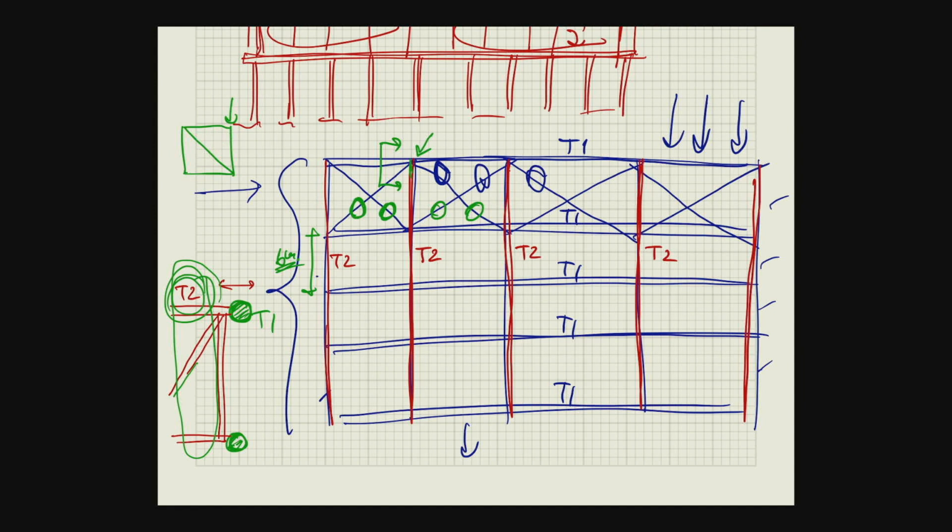Whereas if you have the load in the opposite direction, then this one carries the load because it is in tension, whereas this one is in compression. Compression is going to form some sort of elastic buckling. There is no permanent deformation in your brace as it is really slender. So the brace is generally made of maybe deformed bar or tie rod, whatever, maybe cable. And these components are not going to experience yielding under compression because it's going to buckle, and as it buckles, it doesn't engage the force.